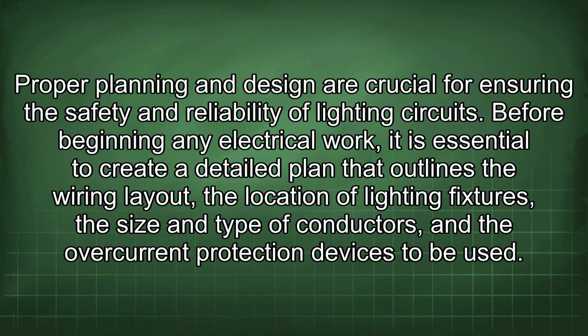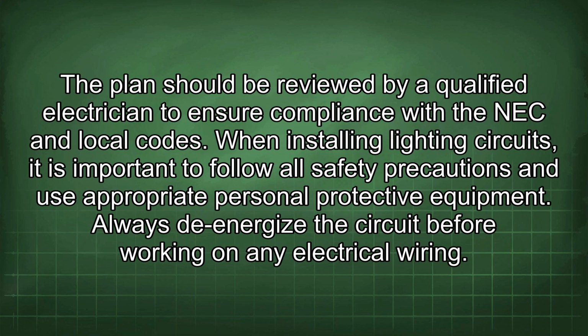Proper planning and design are crucial for ensuring the safety and reliability of lighting circuits. Before beginning any electrical work, it is essential to create a detailed plan that outlines the wiring layout, the location of lighting fixtures, the size and type of conductors, and the overcurrent protection devices to be used. The plan should be reviewed by a qualified electrician to ensure compliance with the NEC and local codes.